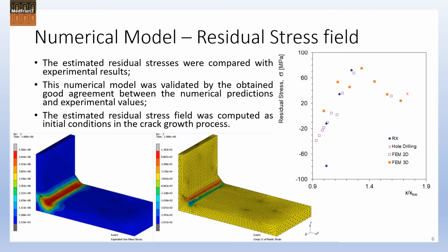The estimated residual stresses were compared with the experimental results. This numerical model was validated by the good agreement observed between the numerical predictions and the experimental values obtained by X-ray diffraction and hole drilling technique. The estimated residual stress field was computed as initial conditions in the crack growth process.